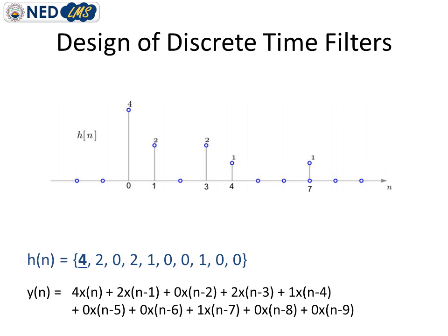As you already learned, the design of an FIR filter is done by first defining the frequency response which we need from our filter, and then we take the inverse Fourier transform of that frequency response, and then shift that transform result to get the filter's time domain impulse response. But it is very interesting that the desired filter coefficients are exactly the same as the impulse response sequence, but unfortunately this is not true for IIR filters.